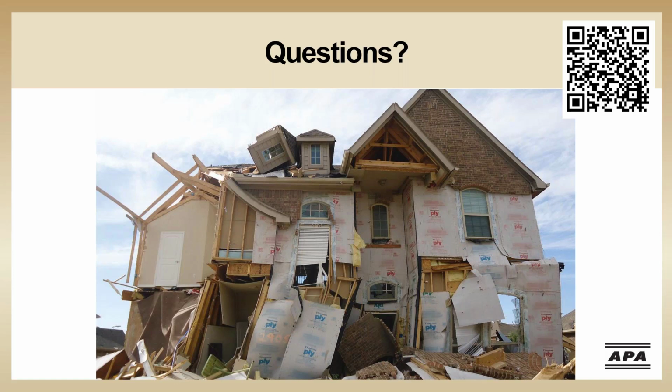We also got a lot of questions about that connection from the second story down to the first story. A question related to that says, you mentioned that if the common framing member at a sheathing joint is blocking above and then below the floor level, the sheathing should also be attached to the double top plate. What nail spacing do I need to use to attach the sheathing to the double top plate? My thought would be it should probably be the same as the required edge fastener spacing. So if it was a prescriptively designed brace wall panel, that would be 6 inches on center. I know the code does not address that specific situation, but that would make the most sense to me.